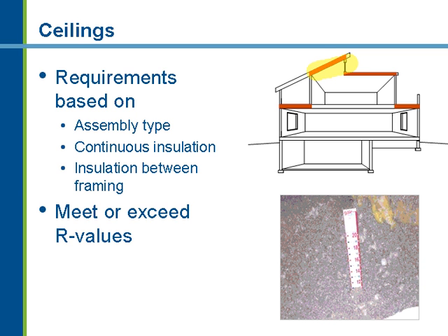If you're using the U factor table, for example, in a UA trade-off approach, you do need to make proper accounting for the fact that the insulation between the framing members has a parallel heat flow path through those framing members, and you have to account for that in your calculations.